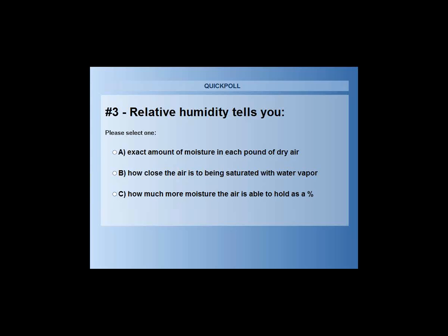400 CFM per ton of cooling would be the maximum that you probably would have for a normal comfort application in the Chicagoland area. But you can drop that down to 350, 325, 300. In some cases you could drop it down to 275, although you might have some situations where you could have refrigeration problems, but you can do it in some units. But 300 CFM per ton is probably the new standard, if you will.